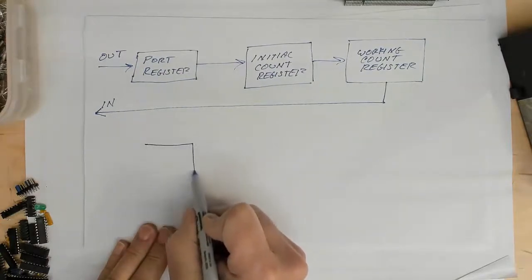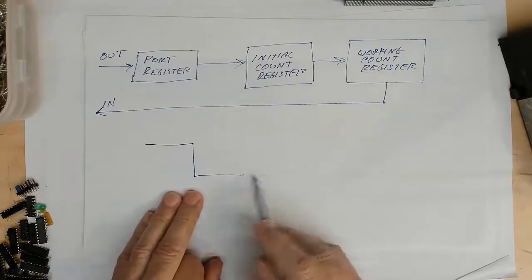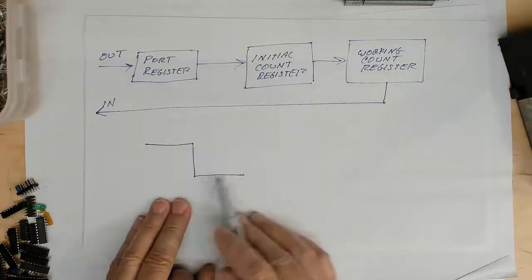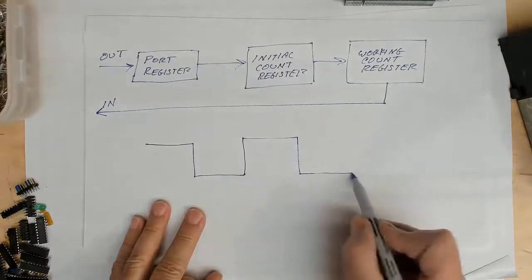Now in the Intel literature they state that the goal of this counter was for it to be able to make a square wave. Okay, the little one-shot mode was kind of a secondary. Their primary drive was to get this to operate as a square wave. And if you have it in continuous mode, of course, this just makes a continuous square wave.